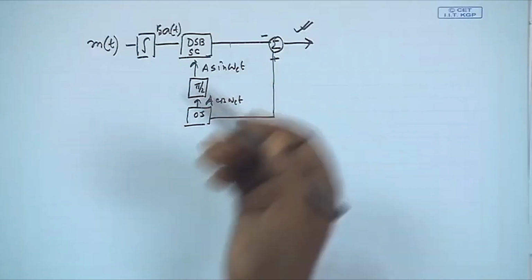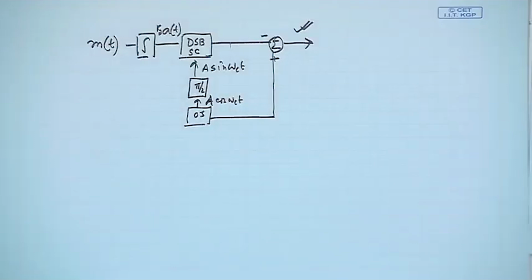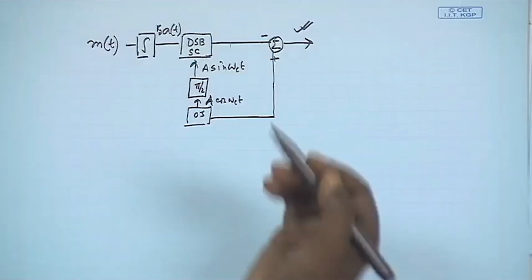For demodulation also, it is very simple, you just do the reverse process, because it is almost like AM modulation or FM modulation. Okay. So, right now we will not talk about FM demodulation. We are just talking about FM modulation. So, this is the way we will be generating narrowband FM, as long as the frequency deviation is small.